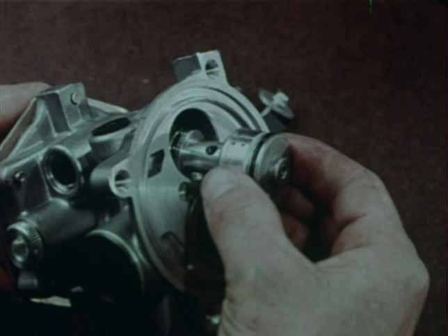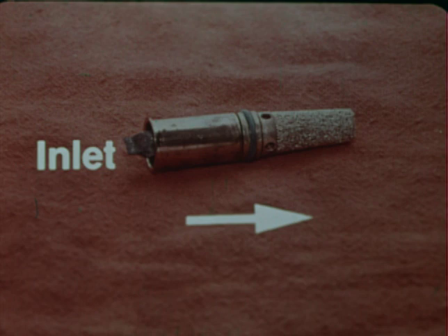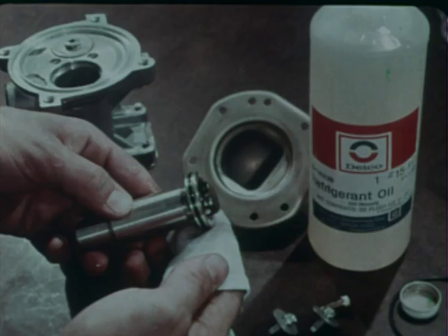In the POA and VIR systems, this is accomplished by a variable expansion valve that is sensitive to evaporator pressure and evaporator outlet temperature. The OTCC system employs a non-variable orifice called an expansion tube. This device is non-adjustable and must be replaced as a unit if it becomes restricted.